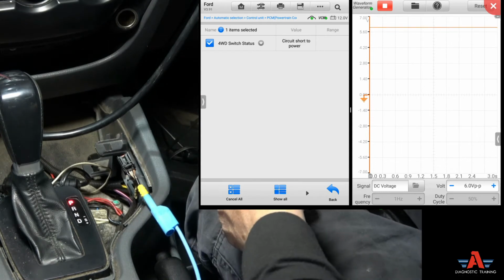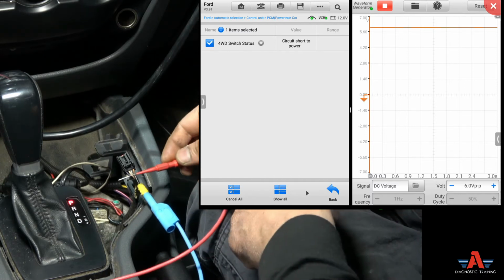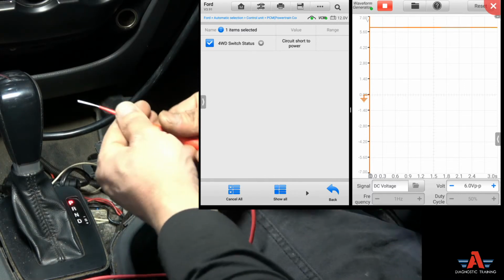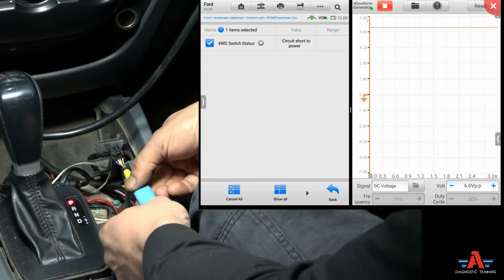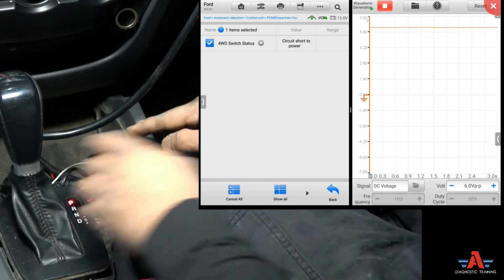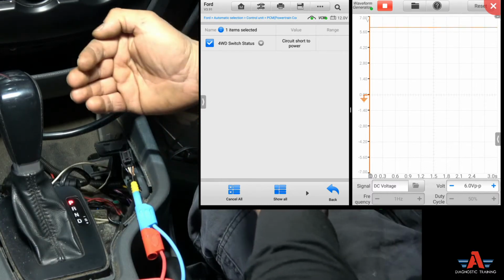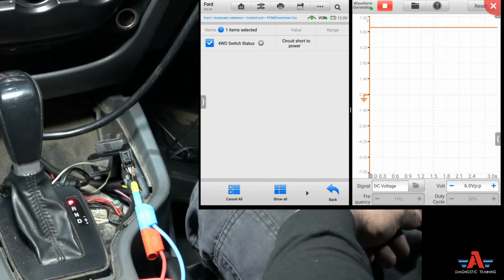Now my ignition is on, and I'm going to short this out. I'll just piggyback that, same thing. I'm just going to put that voltage in that signal wire. Everything is disconnected, the switch is not there anymore. Now you're going to become the switch here, okay, guys? So 12 volts goes in.